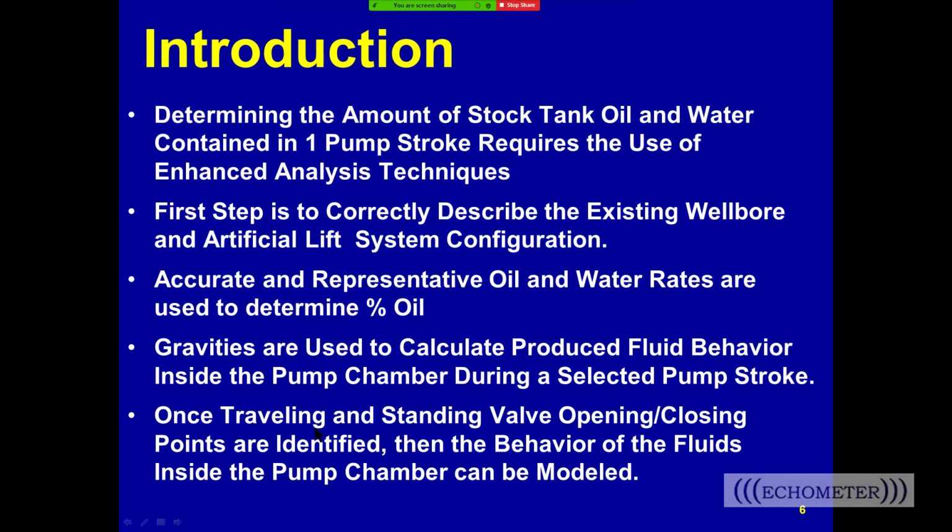The valve opening and closing points of the pump are automatically selected, and they should be at the corners of the pump card, and you should show them, because if they're not positioned properly, the program's going to use those incorrectly located valve open and close points. There are annotations. You should turn the annotations for valve open and close points on if you want to do this calculation, because you need to have the valve open and close points located properly, and we're still working on getting that down exactly correct. And so, if the computer doesn't pick it right, you've got to pick it right.